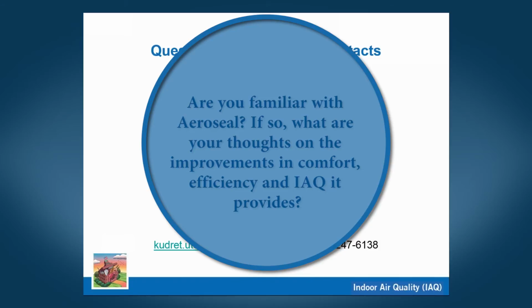The typical fix for duct board is, for many different reasons, to put in real ductwork. Yeah, I agree. Because it's impossible to clean. It was a good idea that has run into many problems with time. Thank you. All right.